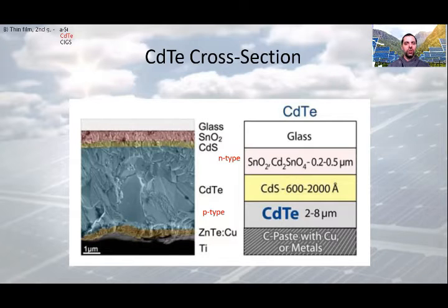A transparent conductive front contact covers the cadmium sulfide, while the cadmium telluride is in contact with the conductive rear surface substrate. The cadmium telluride technology utilizes high throughput fabrication techniques, for example, closed-space sublimation, requiring high process temperature in the region of 600 Celsius.